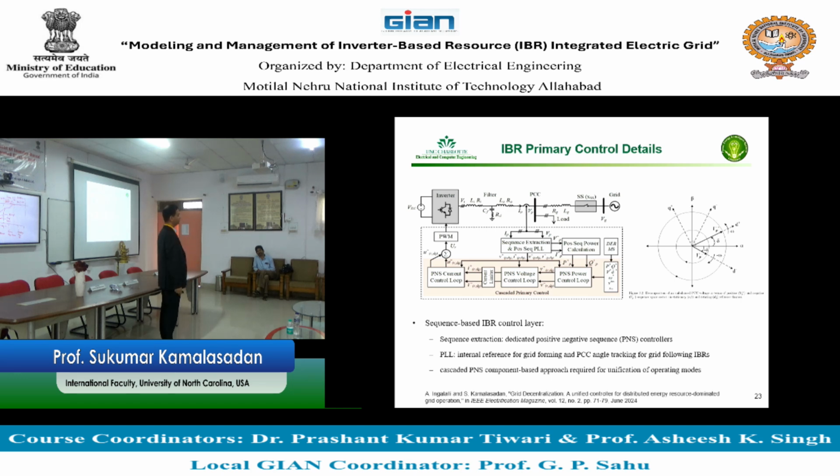Another property of the synchronous machine: if the current goes high, it is going out from the synchronous generator for some period of time. The synchronous generator is not going to die. It is going to like 6 times, 8 times, because it's a property of the machine. Surge current, which we call inrush current, is coming from the machine. That is not there in the inverter.